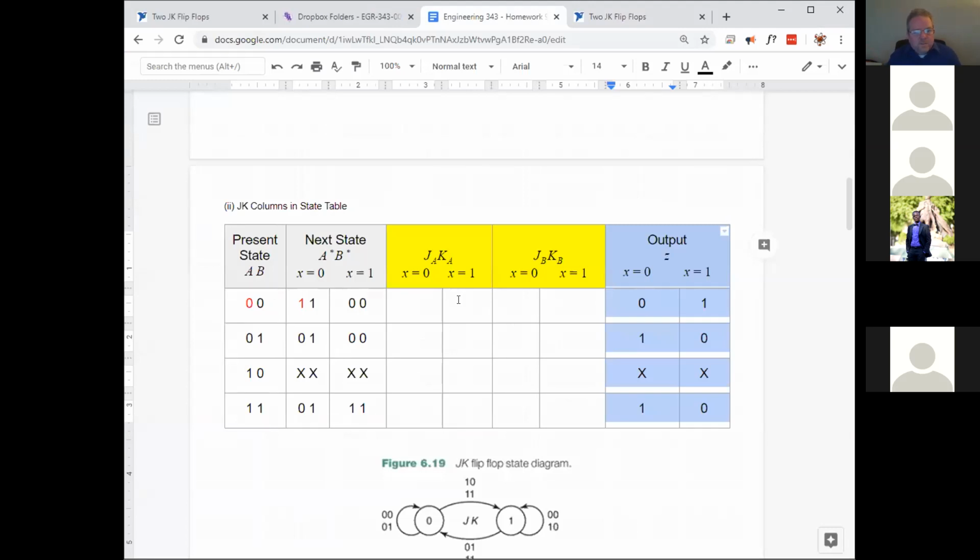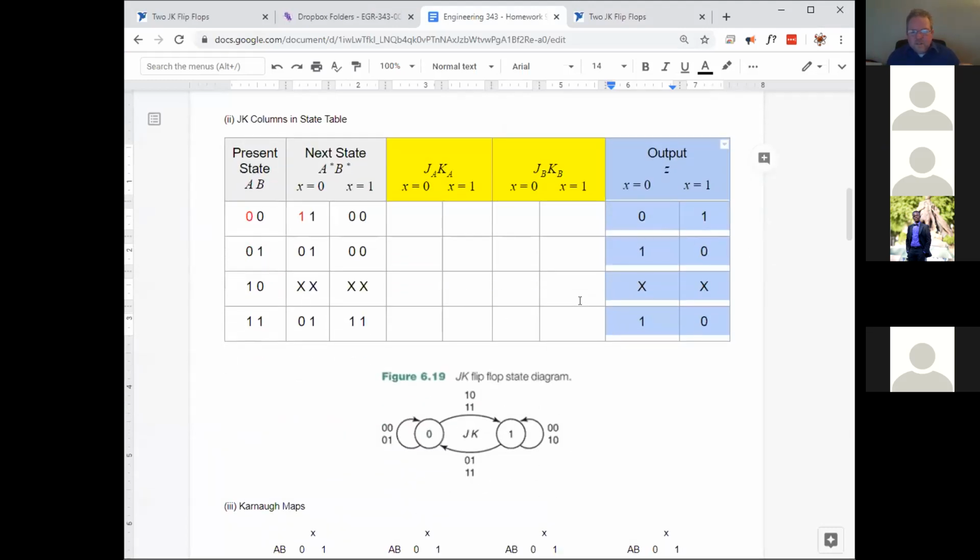All right, so watch very carefully because it requires a couple of careful steps there. And then you'll see it, it'll just become easy all of a sudden. I highlighted two numbers here in red because what we're identifying is the case that if A is equal to 0 and X is equal to 0, then A becomes 1 in the next clock cycle.